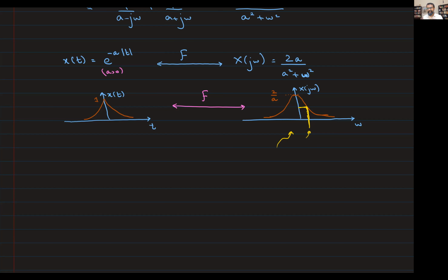But what does higher pitch really mean? Pitch is related to frequencies actually. So now I can tell you this. Once you're familiar with the Fourier transform, if you take Hanya's voice, who's my daughter, and take the Fourier transform of that, and you take my voice and take the Fourier transform of that, you will find that the Fourier transform of my voice is concentrated more at the lower frequencies compared to Hanya's voice, whose Fourier transform is going to be concentrated a little bit more at the higher frequencies.